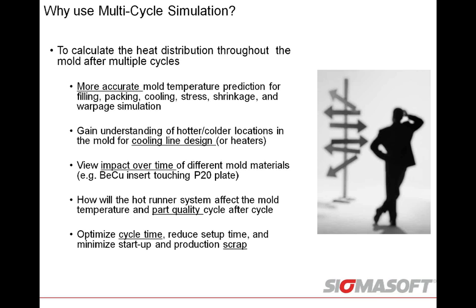And then at the end, optimizing things like cycle time, reducing setup time, minimizing that startup and production scrap. So being able to simulate what's going to happen before you actually put the mold in the machine. How many cycles does it take for that mold to reach a steady state condition? When you actually put that mold in, we don't want to sit and make 30, 40, 50 pieces of scrap because the mold hasn't reached a certain equilibrium yet. So knowing that going in gives us a much more valuable idea to minimize that setup time, but also minimize not only startup scrap, but also production scrap.